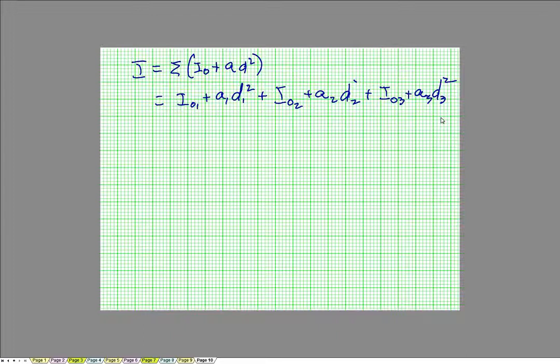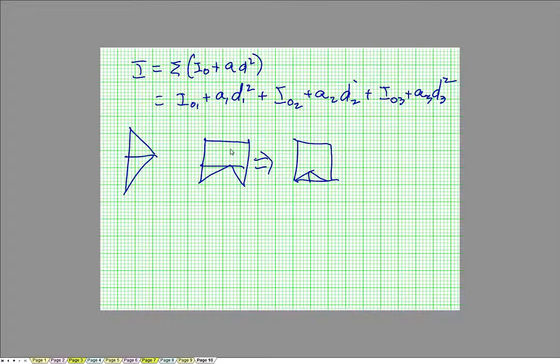So there's actually a process that you really need to worry about, and that is for whatever shape you're given. Let's say we were given something that maybe looks like this, or something that maybe looks like this. We talked about finding a centroid when we're looking at things like this. Break it up into its individual pieces. This one could also be the box subtracting two triangles. So it's either a smaller rectangle adding two triangles, or it's a large rectangle subtracting two triangles. However you want to do that.